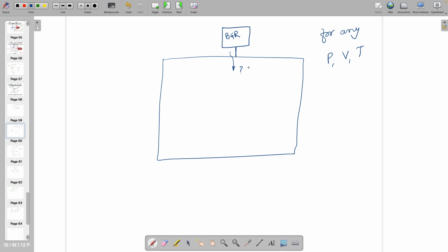because many PMOS are available in parallel. Each PMOS looking from the source side is 1 by gm. So if each one of them gives you an impedance of 100 ohm, and if there are 100 branches, it is 1 ohm, or less than 1 ohm. So this particular impedance is very important to drive all the circuits.